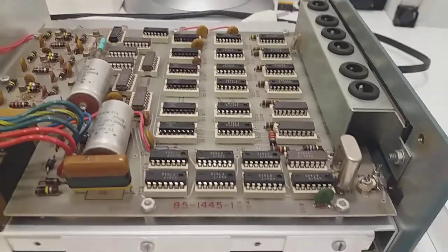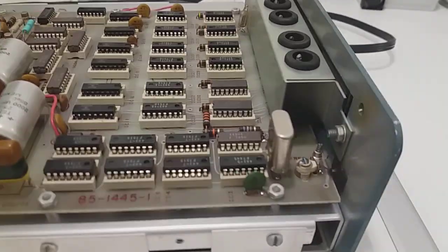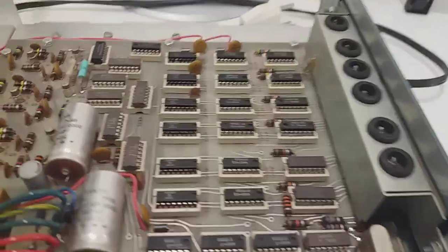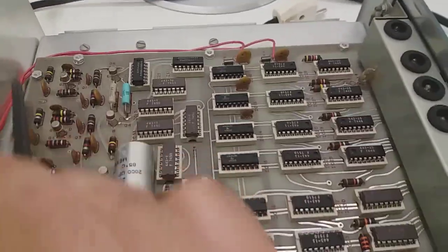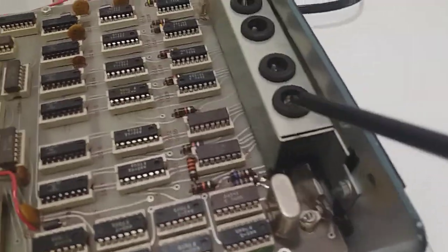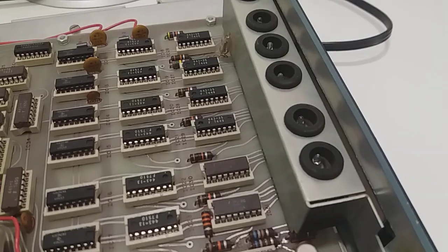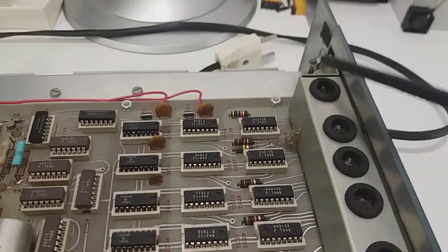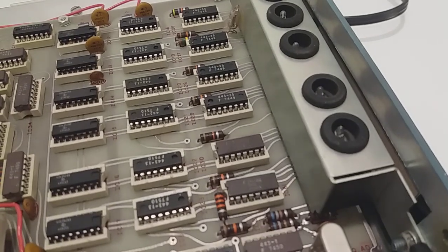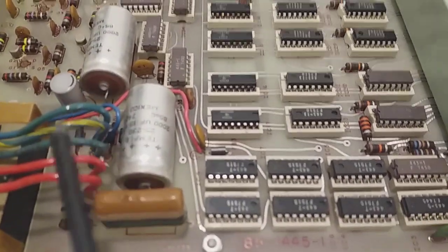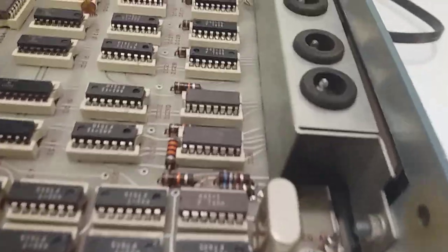Back at the bench. The problem is that to replace this capacitor here, you have to actually disassemble the whole PCB, all those screws, and you have to remove the cover of the tubes, of the nixies, and remove these screws which hold the plastic one. Even then you have those cables here that don't allow you to completely remove the PCB but just bend it over. So it was easier to